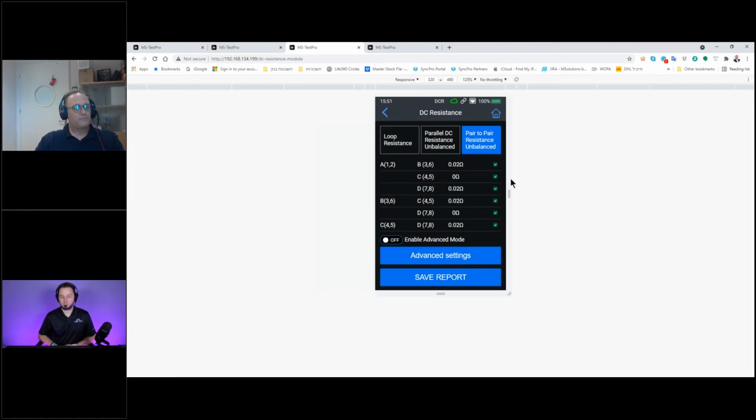So there are real thresholds that we need to apply, and those are not under the IEEE, because the IEEE is directed at LAN more than HDBaseT. Even though PoH is under the IEEE for PoE implementation, it still refers to HDBaseT and is not covered with real limitations.